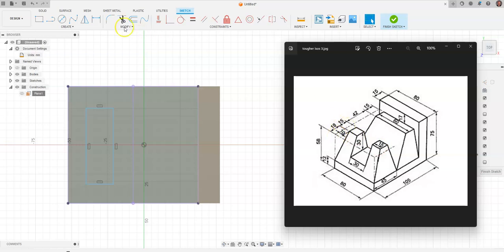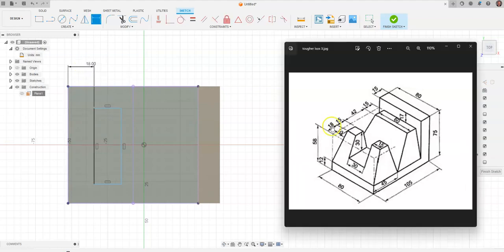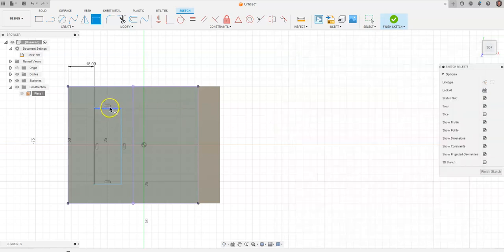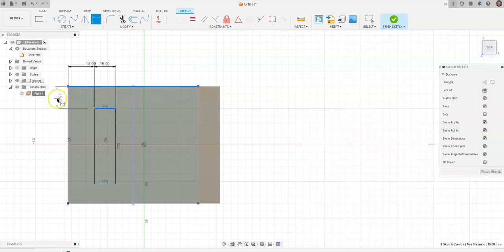So we're 18 in from the side. I can grab Dimension from here to here, a distance of 18. I'll go 18. We go back over here. The width is 15. Hit Enter. Now we need the distance in from the side, and it looks like the distances in from the side are going to be a distance of 10 on both sides. So I'm going to go here, and here, and put in a distance of 10, and hit Enter. Same thing over here on the opposite side, from here to here. I'm going to type 10 and hit Enter.